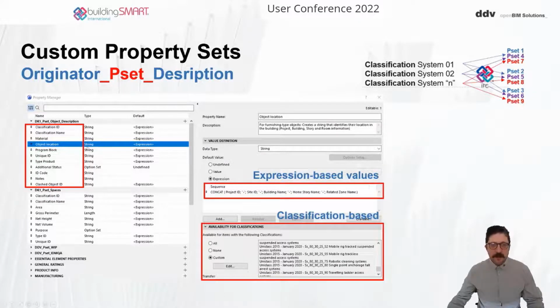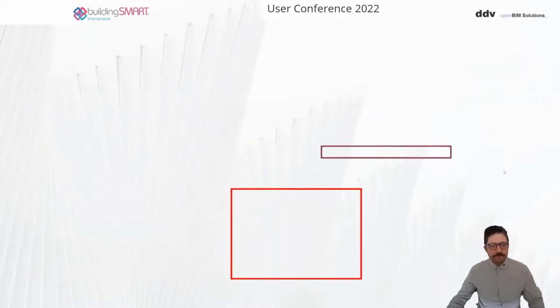So you can define here with this feature called Property Manager different properties, and you can use, as we mentioned, expression-based values, and again, the classification keystone in ArchiCAD, we can map to the different objects, the different geometries that we have included in our model, the different property sets using the classification items as our mapping driver. Okay, this is very, very powerful.